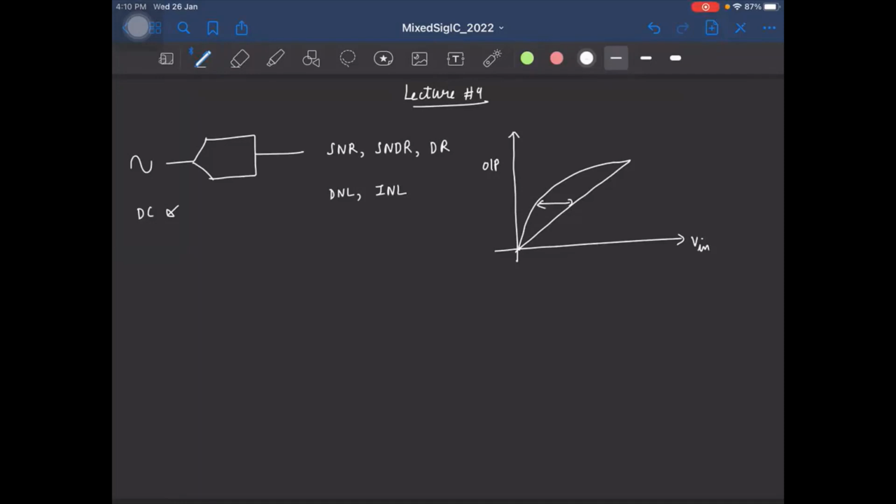right? And this curve says how the output varies as a function of the input, right? So this essentially captures the effect of the nonlinearity, right? So as a result, this signal to noise and distortion ratio and the INL, they are not independent, okay? This should not be a surprise because both SNDR and INL capture the nonlinearity effect of the same ADC, right?